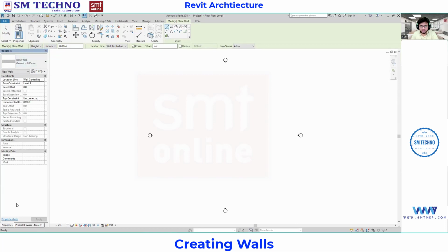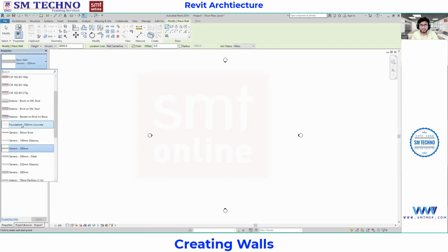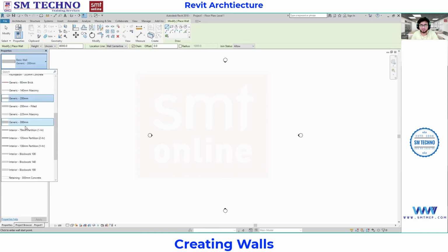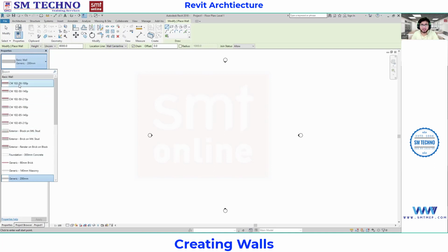In the properties bar, you can see we have got three different types of wall. One is nothing but the basic wall. Can you see the category of basic wall over here? Next, when you come down, in the basic wall we have got these types of walls. Again, you can see we have got the curtain wall. Again, you can see we have got the stack wall. So in the basic wall, select any type of wall.